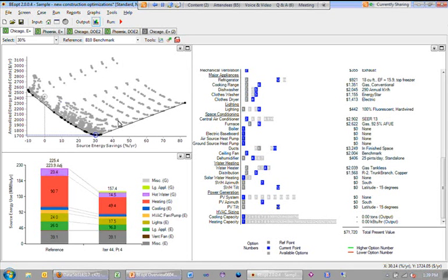so we don't show the entire cloud of combinations. We don't run all those buildings. But there are at least technologies all the way up to here that would have also saved 30% energy savings at over $1,000 more a year. So this is a little bit demonstrating why having the sequential search optimization in BOPT is very useful, because it's easy to come up with a design that saves your target energy savings, but trying to do so in a cost-optimal manner can be very challenging.